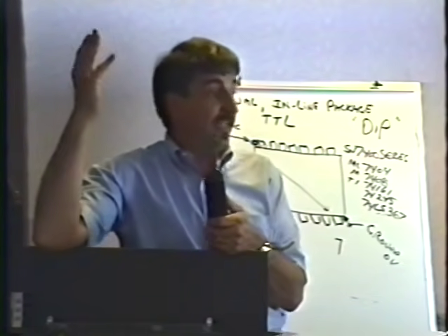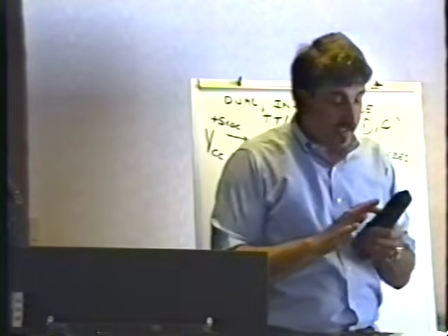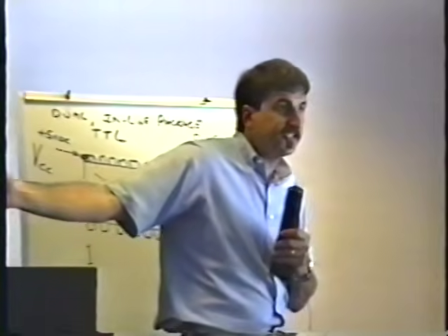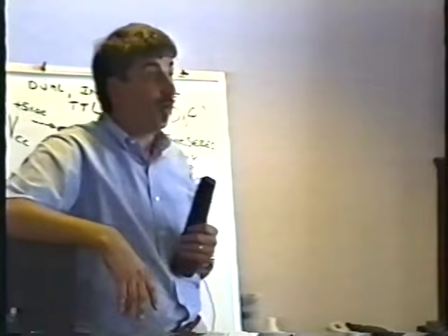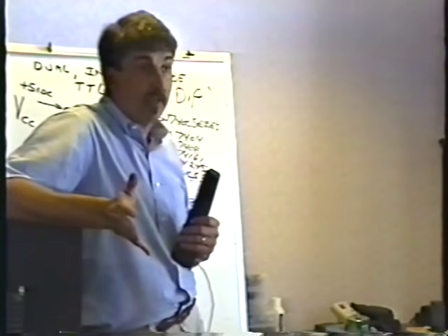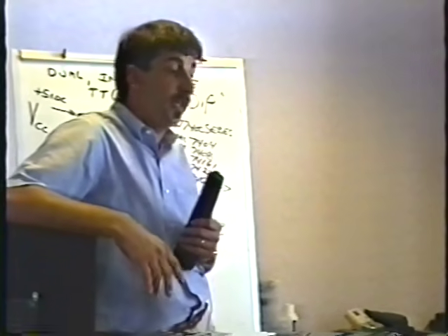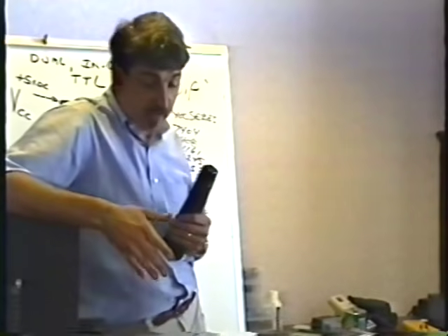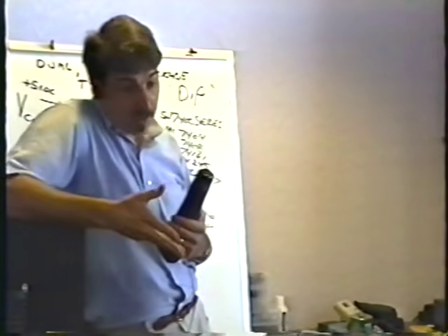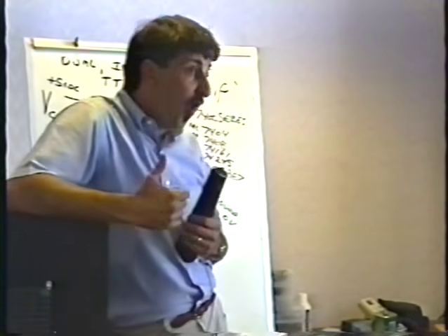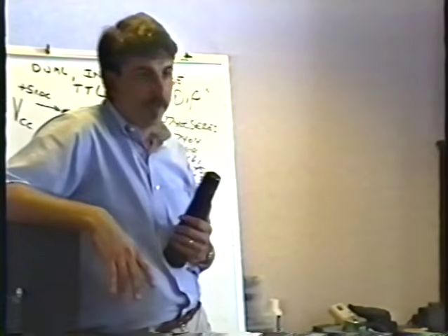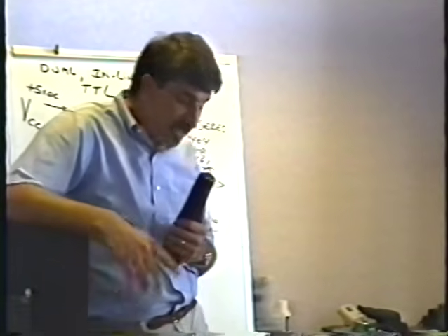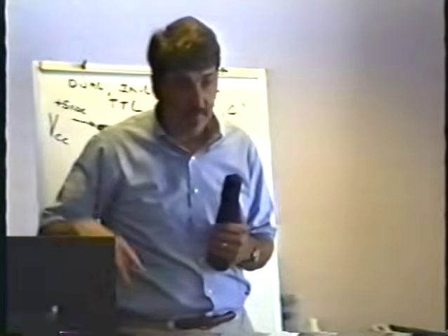And I know, like I said, I'm not a genius. I see this 100 times. I've changed C702 in 100 different monitors. Because I do these monitor labs on the road all the time, I see tons and tons of monitors. It's almost all I work on, really. I work on monitors in the field, on the road when I'm here doing the classes. And when I get home, most of my repair work is monitors, because the other people can do the simple jazz, and the monitors, they just don't know. So I've changed this cap a ton of times.